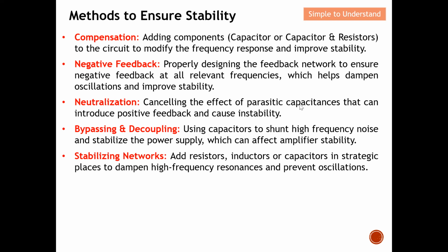Okay, so basically we need to cancel any form of parasitic capacitor, because they can potentially create positive feedback. And in order to prevent this, we need to cancel away the effect. Bypass and decoupling: basically, bypass and decoupling capacitors can shunt the high frequency noise.